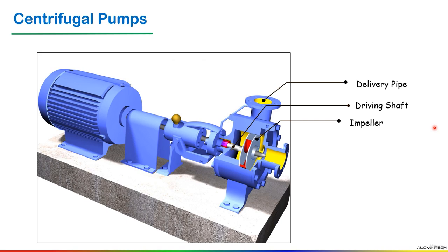We have different types of impeller: open impeller, semi-open impeller, and closed impeller. Open impellers have the vanes free on both sides and are typically available in small diameters. Semi-open impellers have the vanes free on one side and enclosed on the other, and can be used in medium diameters. In the same way, a closed impeller has the vanes located between two discs, all in a single casting, and is used in large pumps. So this is about the impeller.